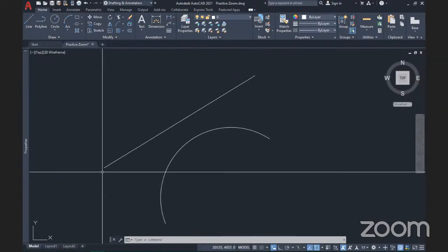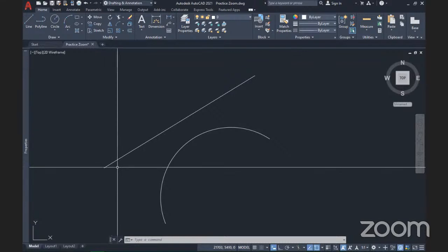So how can you see the points? Since a point does not have any size, how do you see this point? If you remember from our previous class talking about points, I talked about how to edit this point. And there is something called dynamic dialog point type. Okay, now this DDPTYPE, that's the command. It helps you edit the properties of points to make them more visible.